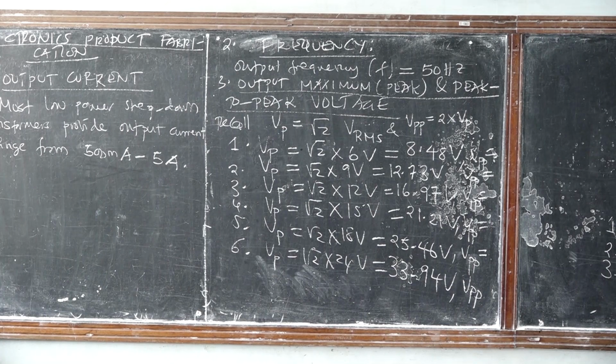If, for instance, the total amount of current that will be consumed by your system is 2 ampere, and you choose a step-down transformer of 12 volts providing a root mean square current of 1 ampere, then your linear power supply will fail to power your system, because your system needs a large amount of current that the transformer cannot provide. Are we together?